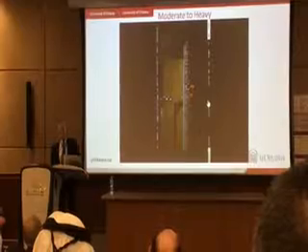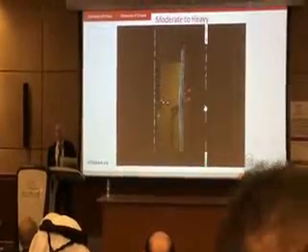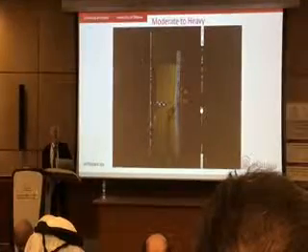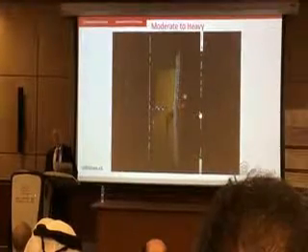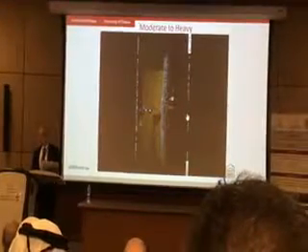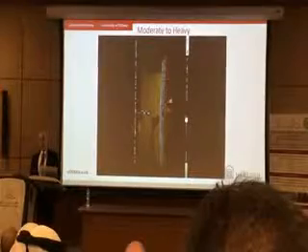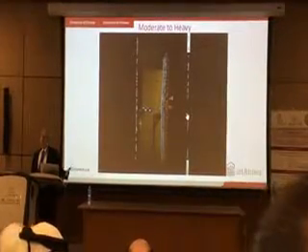Now, moderate to heavy is acceptable depending on how much repair you want to do. And this has a little bit of permanent deformation, but it can possibly be repaired. So this is B2 performance level. You see, these observations are linked with response quantities.